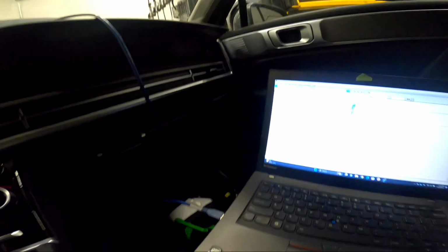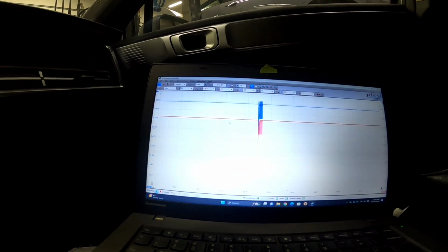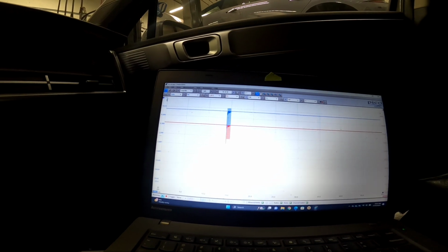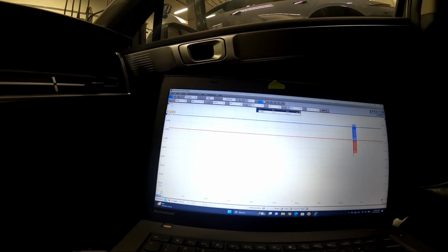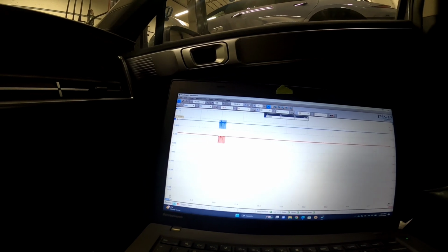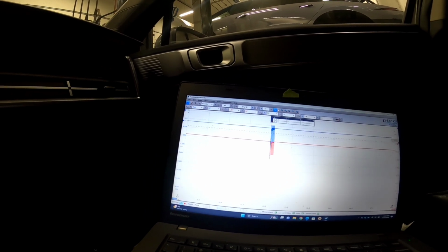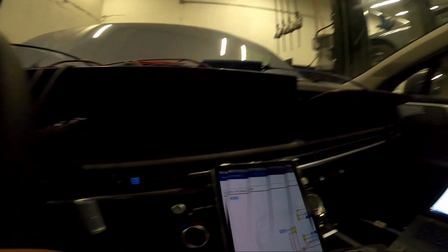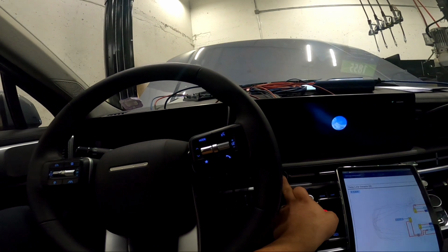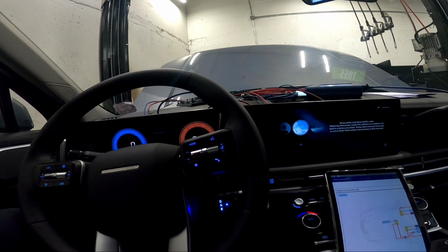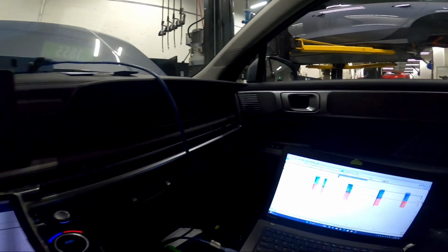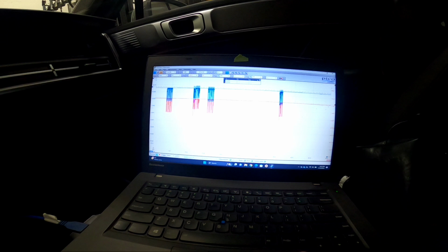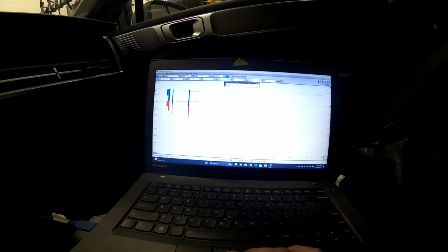Now I use my Pico so that we can monitor both CAN wires. So we still have, with ignition off right now, 12 volts. That's reading battery voltage, the same thing as on our low, right? 12.3. I'm gonna do ignition on. Let's see. Okay, and we have our capture right now. Put more time here, let's see.